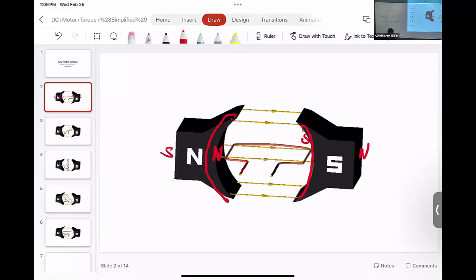And in a motor, I'll show it in the document camera a bit later. We have two magnets inside. One face is north, the other face is south. And then the flux lines flow through the shell itself. This is an iron shell. So the flux lines will flow from one south to the other north through the back shell that we have. So there are no monopoles.